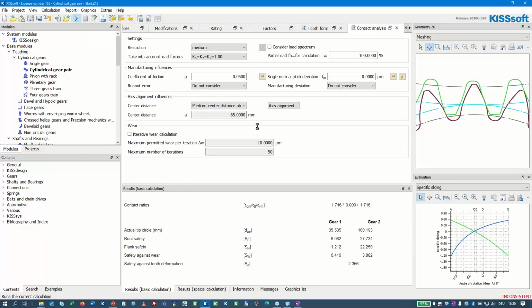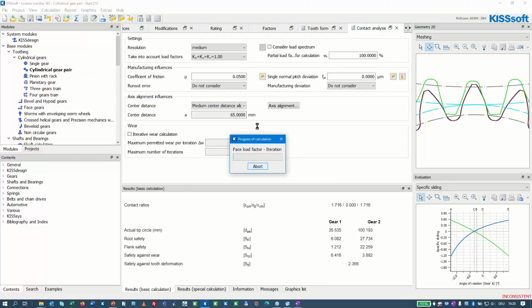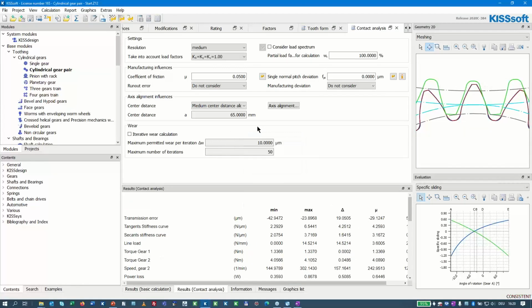If you have a fairly high temperature plastic gear that is stiff in high temperature and you want to achieve zero backlash, then you have to pre-tension the mechanism, if you want to have exactly zero backlash. If you allow for a small backlash, then you have to use what is called here, let me finish this first, the draft angle. So we apply a draft angle.